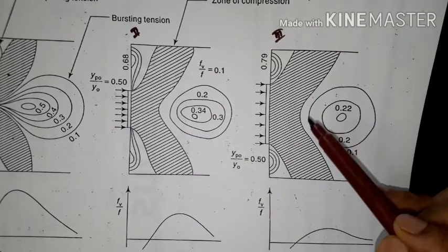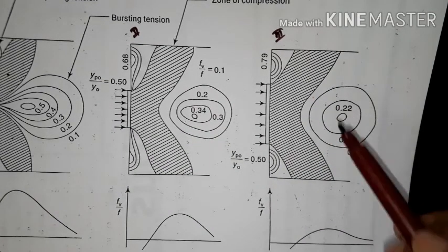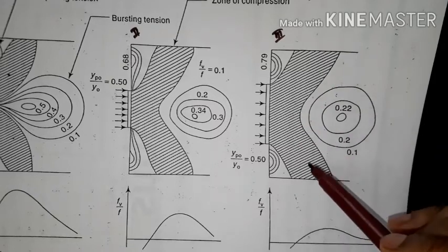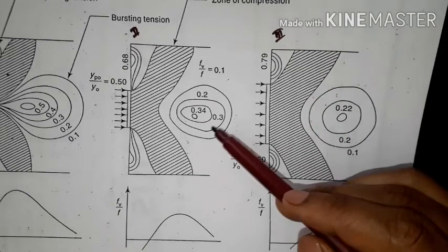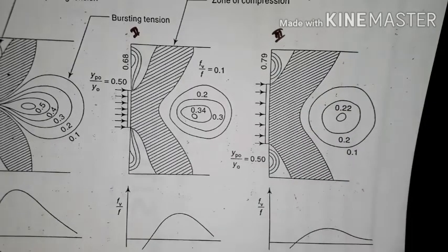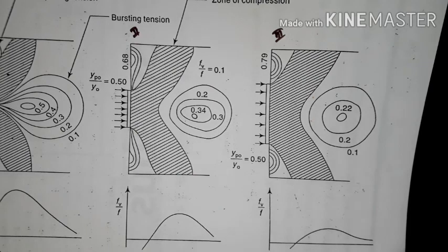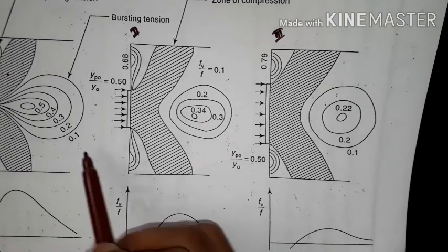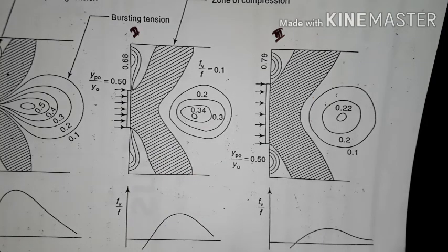But again in zone 3, compression increases and tension decreases compared to zone 1 and zone 2. What is happening here is, as you move away from the anchorage device, the tension is reducing, and no transverse stresses develop in the concrete but compression stresses are developed.